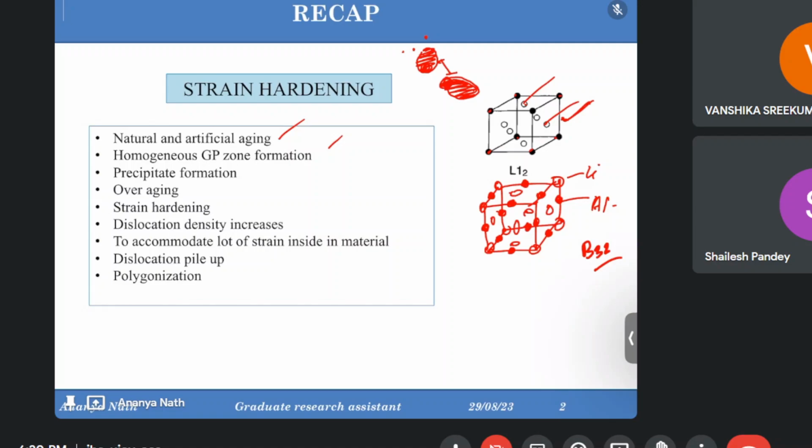So 8 means fully hardened, or 75% or 80% reduction has been done to the cross section, and the lowest strain hardening by cold working is H12, which gives us 20% reduction in the cross section. So we are stretching the material.